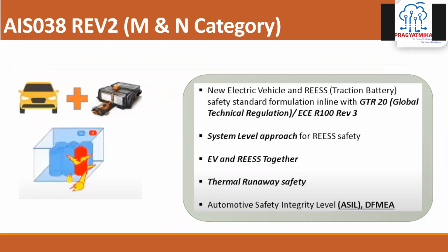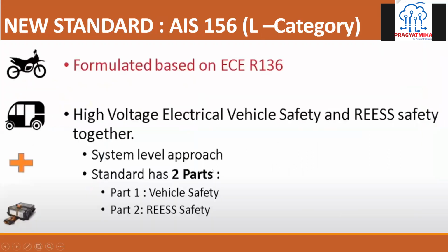And the system level approach is followed in this AIS 038, where the vehicle and the battery pack are taken together. And in this, they are doing the thermal propagation tests also. The BMS which you are using for this should be ASIL D compliant. It is the automotive safety standard. So whatever the chipset is in your BMS, it should be ASIL D compliant. That's what the requirement is.